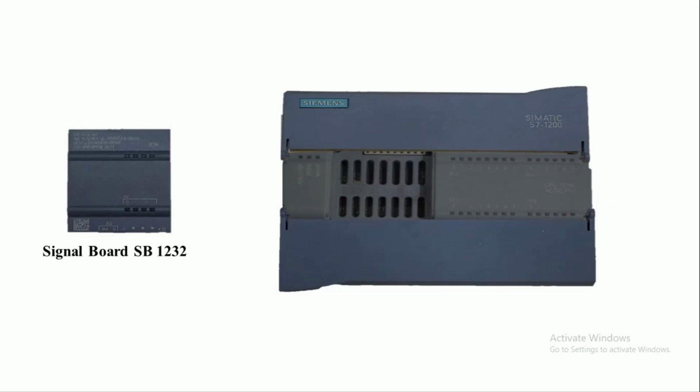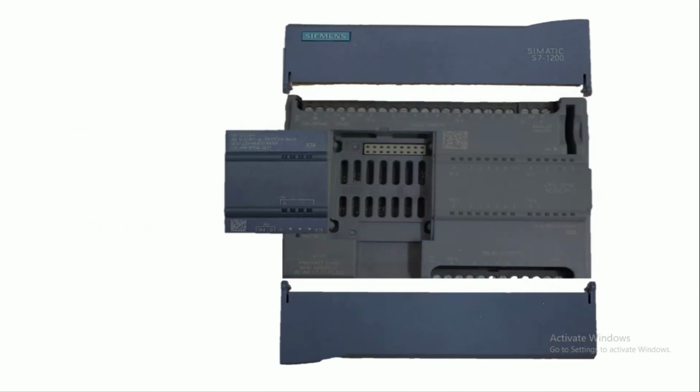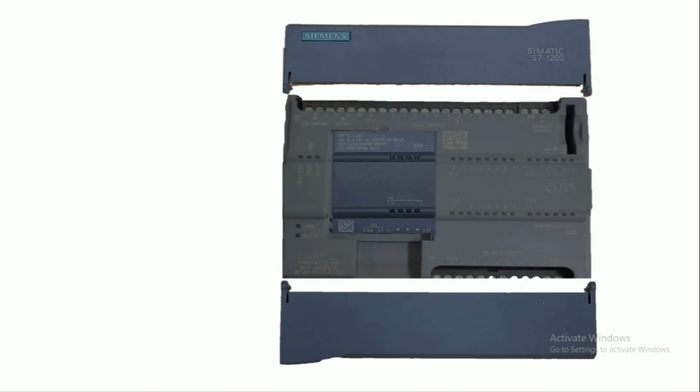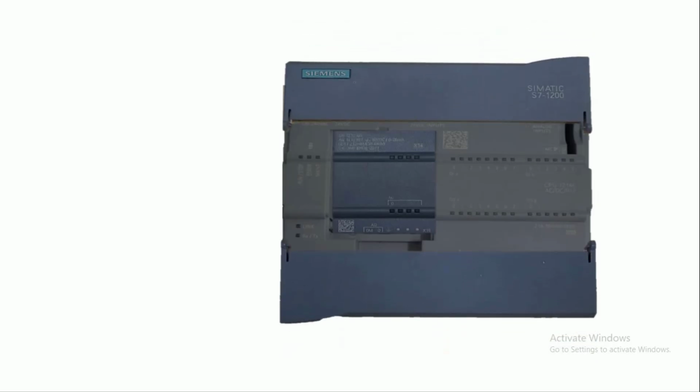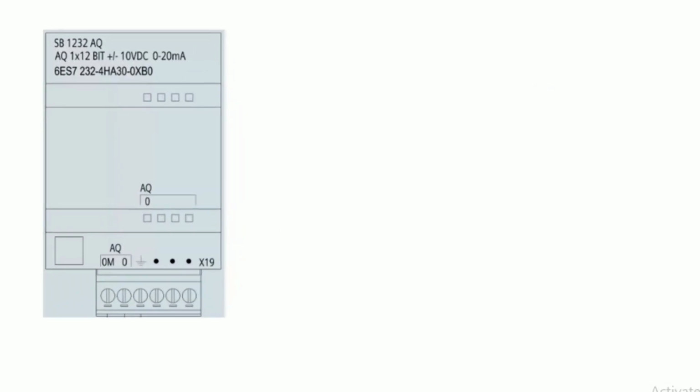To mount the signal board on the PLC, first power off the PLC, remove the CPU's top cover and securely snap the analog output signal board into the designated expansion slot, and finally attach the CPU's top cover to the PLC. After mounting the signal board, the terminals on the SB1232 signal board will be found as positive terminal 0 and common or return terminal 0M.